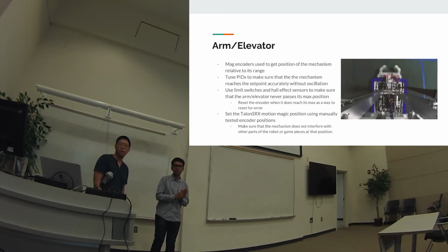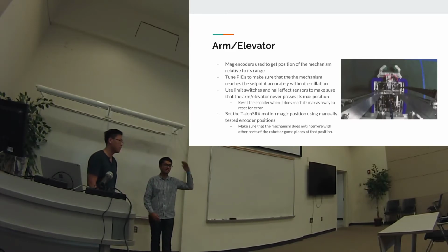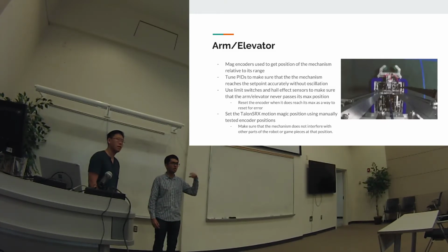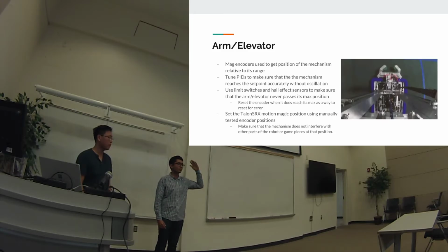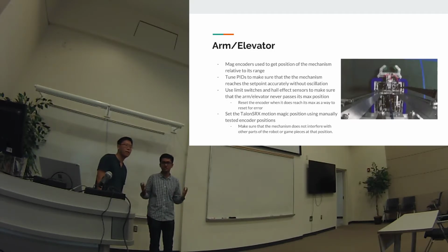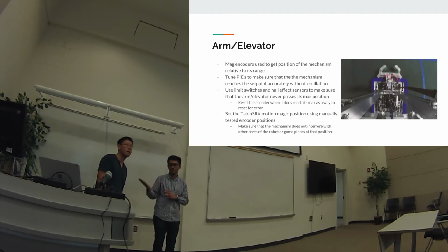This is useful because you might have seen previously, for example at our Columbus event, we had a problem where a robot would go all the way to the max height and start to hit the top of the elevator. This was before we had a limit switch there. So once you put the limit switch, if it would ever hit the top, it would switch off the motor and reset it to the bottom. Once it reaches the bottom limit switch, it would start again. So you're resetting your control loop and making sure that it's safe and nothing's going wrong with the robot, which increases its life.